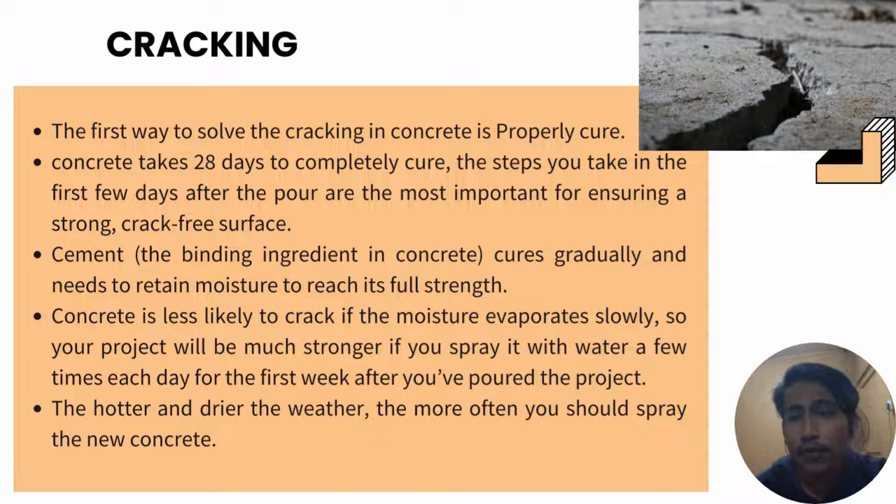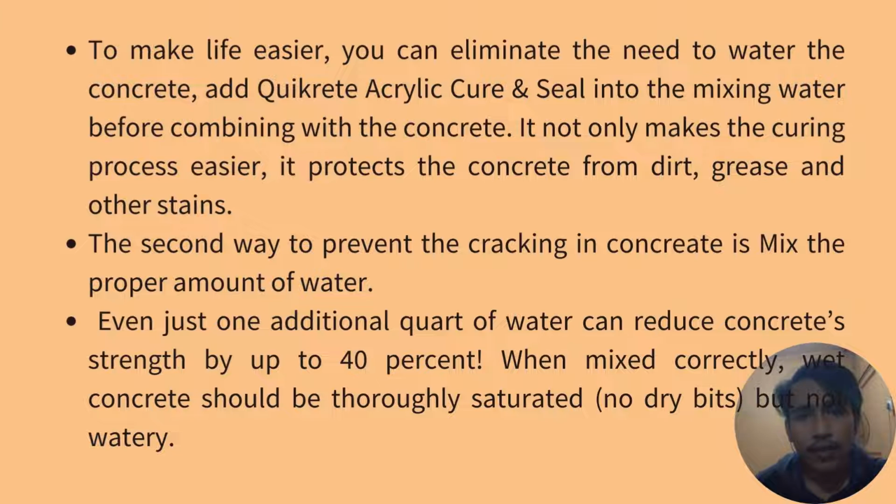So your project will be much stronger if you spray it with water a few times each day for the first week after the pour. The hotter and drier the weather, the more often you should spray the concrete. To make life easier, you can eliminate the need to water the concrete and add a quick-dry acrylic cure and seal. It not only makes the curing process easier, it also will protect the concrete from dirt, grease, and other stains.